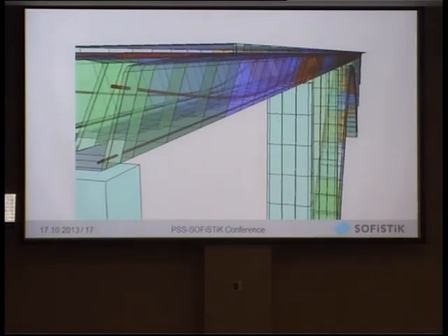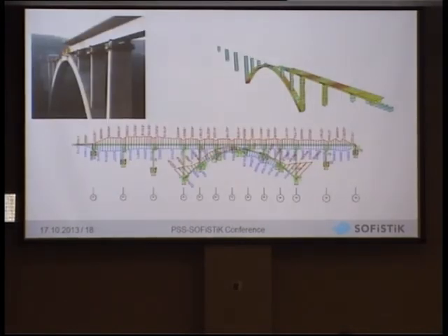So we have these parabolic shaped tendons here in the webs. Here some pictures of the results. So one, there was the construction stage analysis using specific moving spring elements in order to maintain the contact over the piers of the superstructure. And below you see one very important picture.